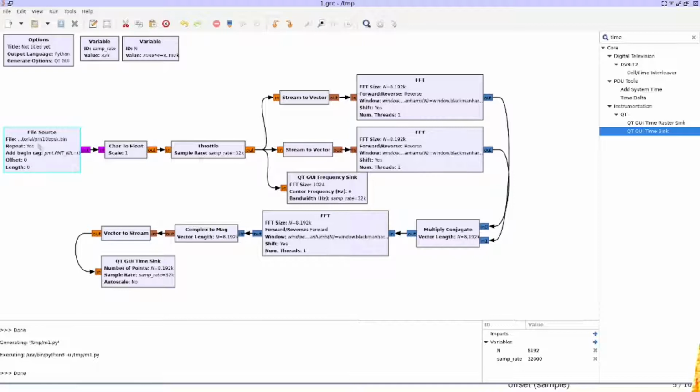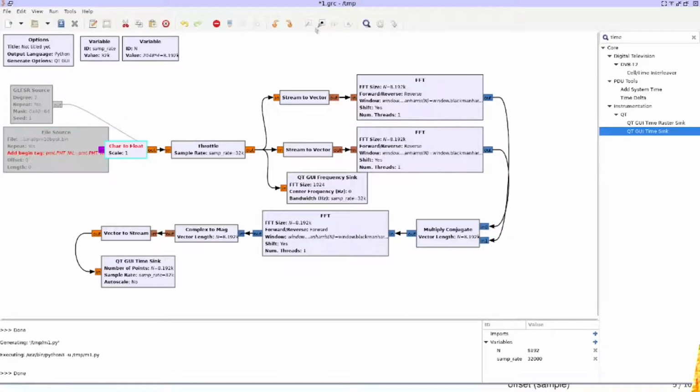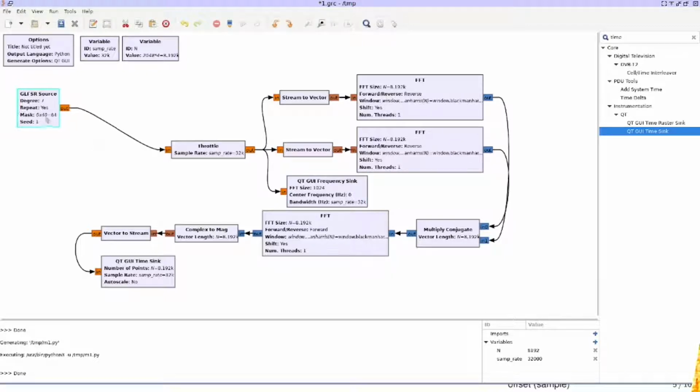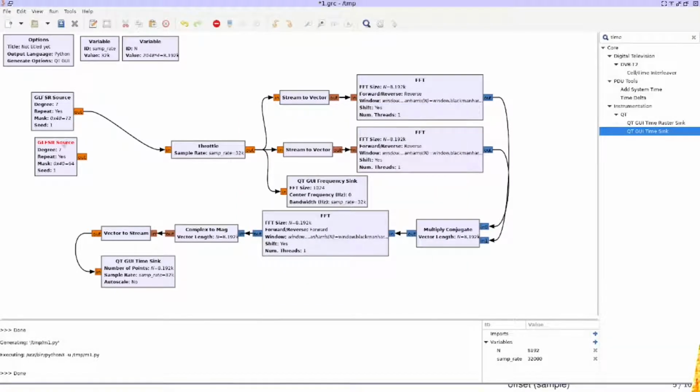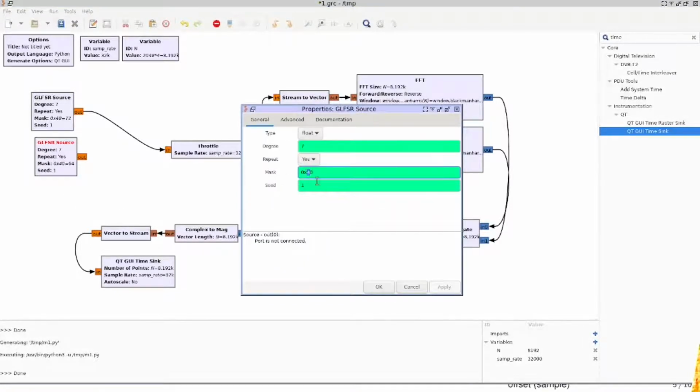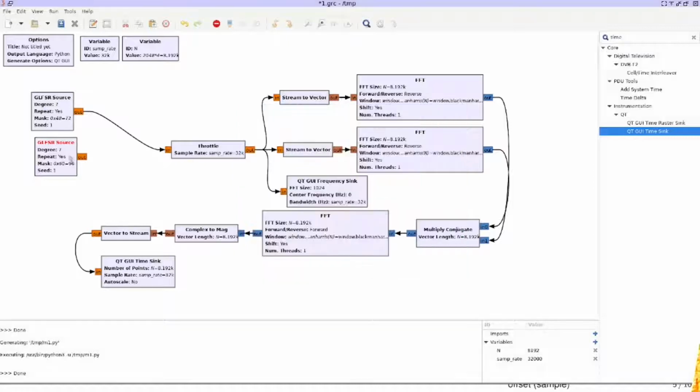Now, say we want to go back to our previous LFSR source. So let's comment this one out over here, and let's go back to our pseudo-random sequence over here. The reason why I kept these two Fourier transforms separate here is that I would like to see what's happening if we have two LFSR sources. Remember, the two possible tap positions were 48 and 60 if I take my previous slide from before. And we've seen earlier that these are two